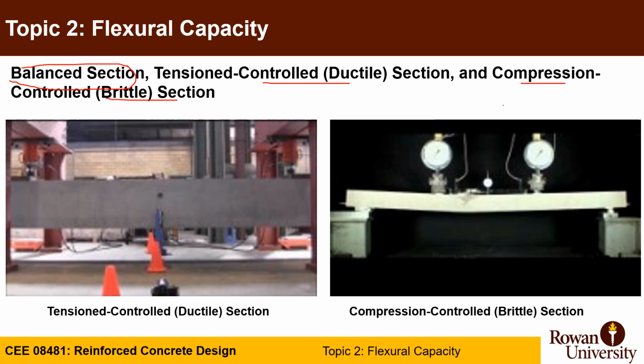So as you can see here, multiple cracks generate along the length of the girder as we load it, and this ductility that we achieve can give you a warning sign to evacuate. However, in compression control section, brittle section, concrete crushes before steel yields. You may have an issue during the recording that those videos will not be displayed.